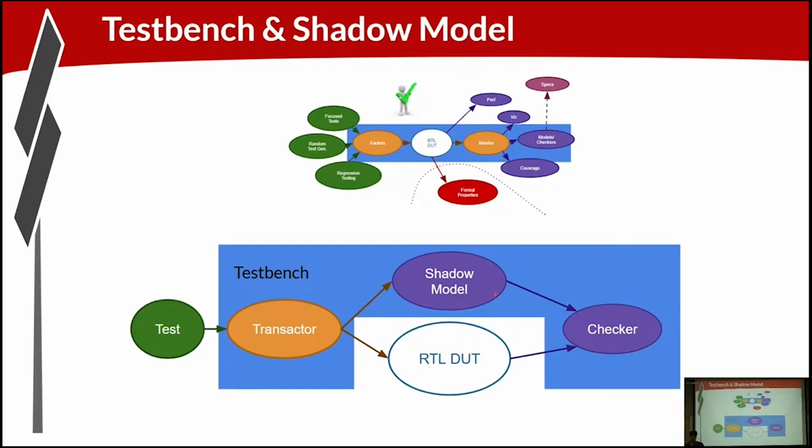What tends to happen when you take this approach is that the gory details of the RTL tend to get exposed, to the extent that the shadow model has to pretty closely match what the RTL is doing. You really get value when you can abstract things. So a shadow model tends to force you into a low level of verification.